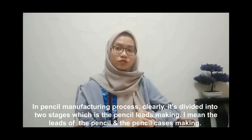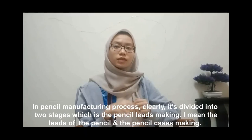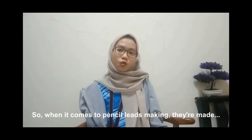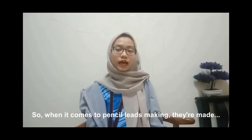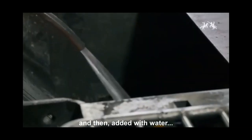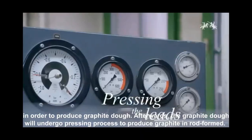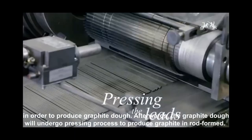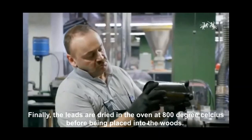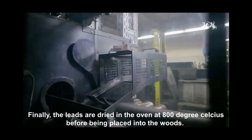The pencil manufacturing process is clearly divided into 2 stages, which are the pencil lead making, the lead of the pencil, and the pencil case making. When it comes to pencil lead making, they are made by mixing ground graphite and clay as inputs and then adding water in order to produce graphite dough. Afterwards, the graphite dough will undergo a pressing process to produce graphite in rod form. Then, the graphite rod will be cut into leads. Finally, the leads are dried in the oven at 800 degrees Celsius before being placed into the wood.